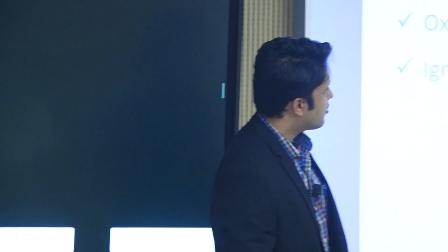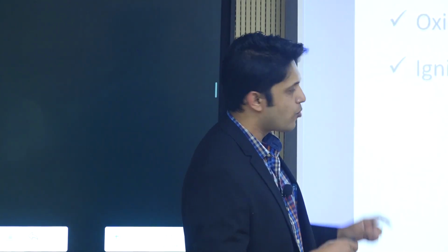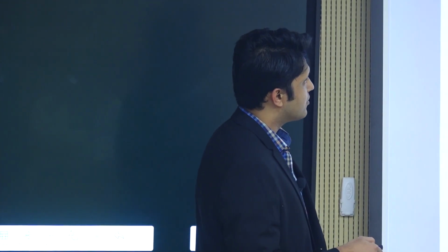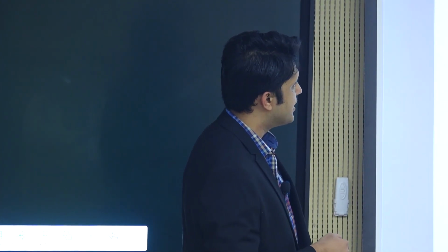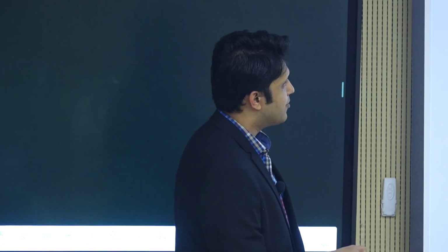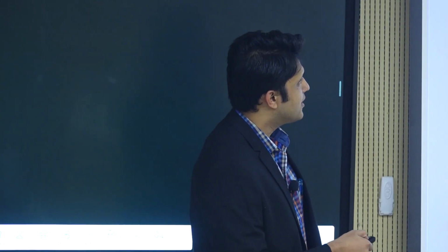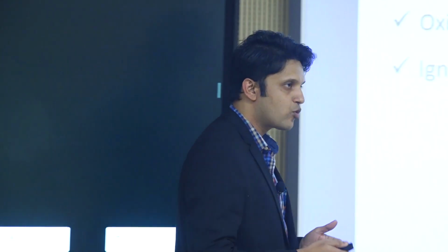So on this right hand side, these are basically small transparent combustor cavities, and what we have is a spark plug that gives the ignition energy, and you can see the flame front propagating, right? These are captured using high-speed cameras at probably 4,000 frames per second. So that is why you can see the flame propagating in real life. But you can see the time that it takes. These are milliseconds. So in 20 milliseconds, the combustion process is done, right? So we use this kind of diagnostics to visualize how the flame front is propagating.